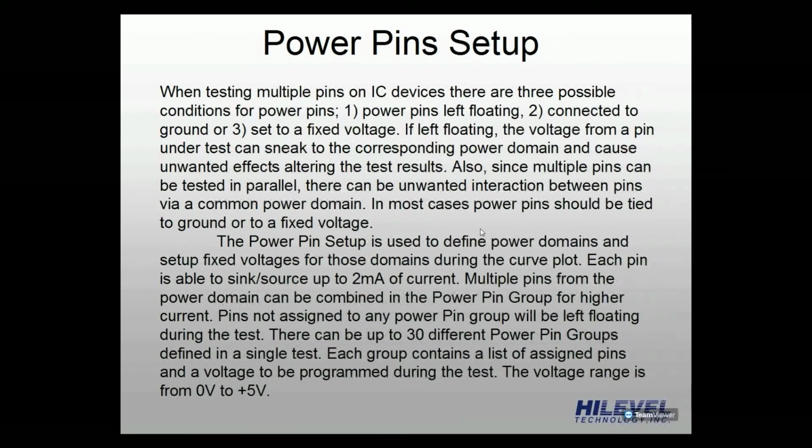Probably not. If your power pins are floating, then some of the current applied to the pin under measurement could sneak onto the power rail and affect your results in a way that is very hard to predict. It may trigger some internal logic and attempt to power the device, putting it into some state that you're not aware of. Generally, you want to set power to some fixed voltage. In the majority of cases, you want this voltage to be 0 volts, basically ground.